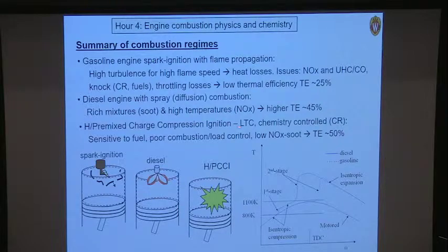Generally, these are restricted to low temperature combustion because the equivalence ratios are low, so you don't get much heat release. The combustion process, the ignition, is chemically controlled, so it depends a lot on the compression ratio. It's very sensitive to the type of fuel, its octane number, for instance. Also, it's difficult to control the combustion process because it's so sensitively dependent on parameters such as the intake temperature, the amount of residual charge, the amount of heat loss due to heat transfer.